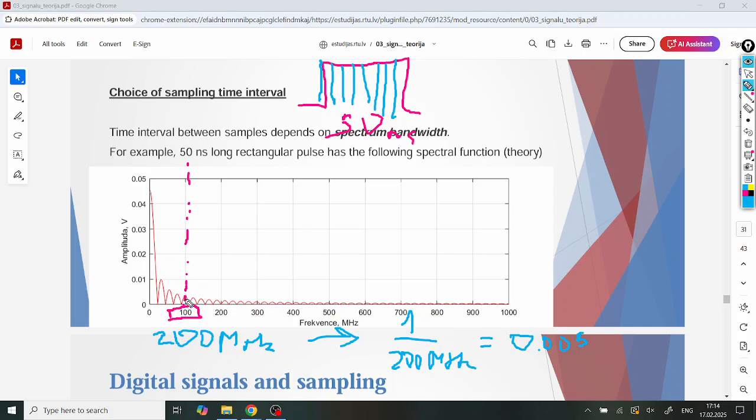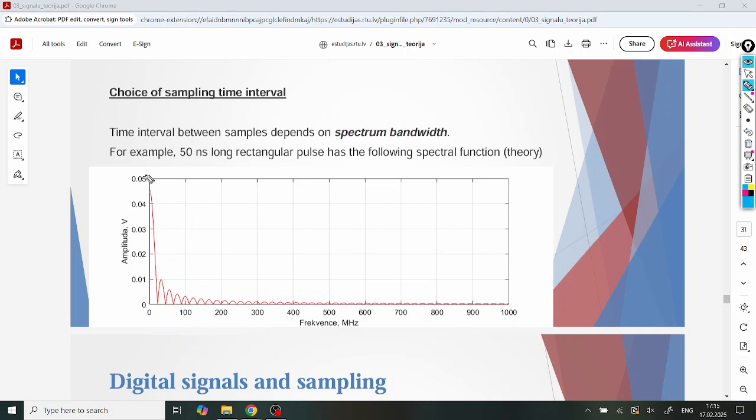But we have been deciding it based on this choice of maximum frequency, because to some extent it depends on our decision. What is this maximum frequency? We have to choose it, yes, based on some conditions. For example, considering that their total energy is like 5% of your signal, or maybe some other criteria. Now, is it safe to say that if I were to decide my limit here, I would be fine? Well, from the perspective of being able to reconstruct it, yes, but there will be some other very unpleasant effect coming into play called aliasing.